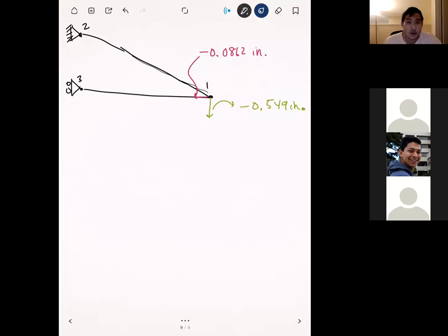Yeah, it's a good question. In these types of problems, they're always going to occur in pairs. You should never get a case where you have just a column that's all zeros, but the corresponding row is not zero. They should always appear together. If you are getting a case where just a row is zeros, but not the column, then I would go back and check to make sure that you put things in the right places when you did the assembly and the boundary conditions.